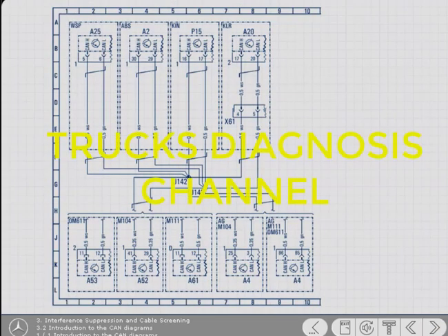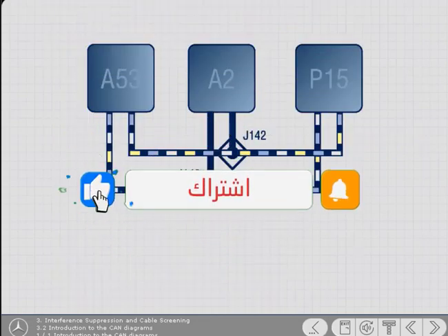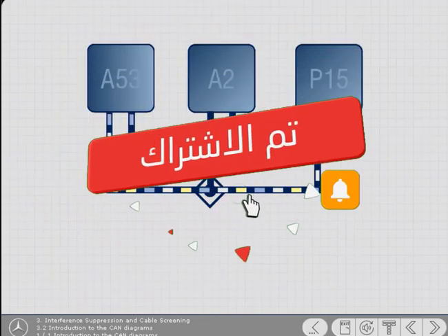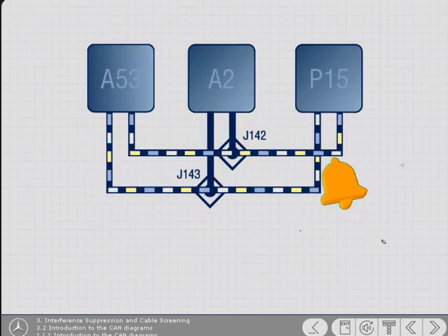This is an example of a CAN wiring diagram for a Mercedes-Benz Vito. The CAN system is a two-cable system that communicates digital messages bidirectionally between the different control modules. The system transmits data at high speed and helps to reduce the number of electrical cables by transmitting different messages along the same two cables. The two cables are known as CAN low and CAN high. Two identical signals are transmitted down both cables simultaneously, but are inverted to each other to reduce the risk of interference.